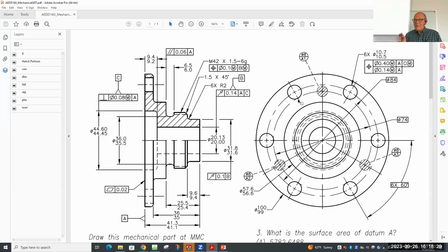And that's a case where you have a place in a machine shop that can make better parts than the parts you're making. And that goes back to the idea that if that surface isn't flat enough, there's no point in measuring everything else from it. If I give you tooling to hold something and the tooling to hold something isn't more accurate than the thing I'm holding, then the thing I'm holding can't be controlled. So if I give you something that clamps and the whole clamp is able to do this, and then I try to put a hole that's really accurate in the thing that's being clamped, it's not going to be accurate because the holding device, the fixture, is not accurate itself.